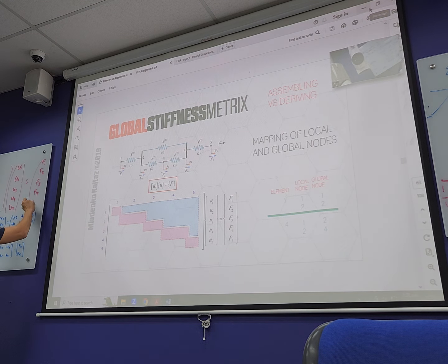Yes. Correct. You will see that in this kind of cylinder matrix, it will always be symmetrical, so that you can inverse it. If your Excel cannot inverse, that means you got a calculation error for sure. There's no way it will not inverse, because you see it always starts with K, negative K, negative K. Likewise, the number of degrees of freedom will be the same as the number of external forces.